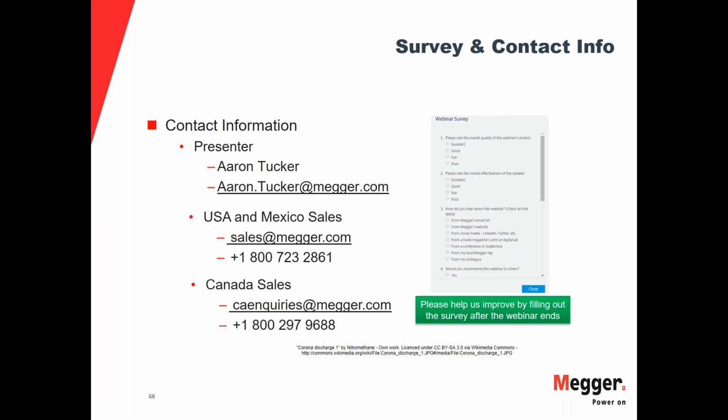Now, for some transformers, for example, when you have a voltage dependency because of the design of the unit, it will be better to do a step-up test. And now, how do you determine that? Well, if you test your transformer and you get results that are outside the acceptable criteria from IEEE, the 0.5% from the nameplate value, then you might want to try either doing a step-up test or a higher voltage test.